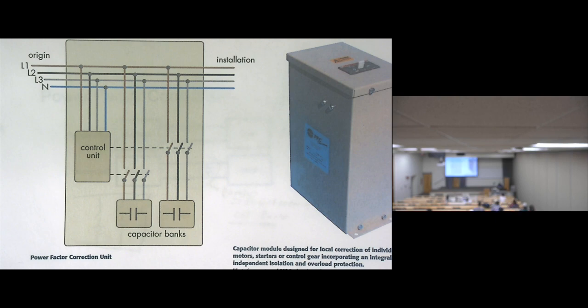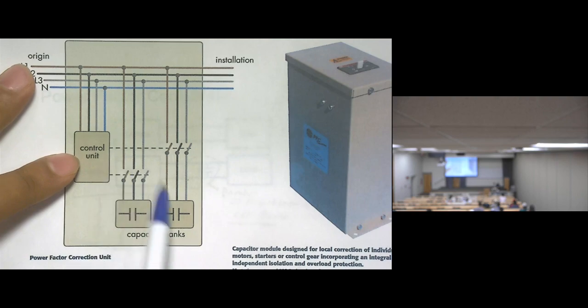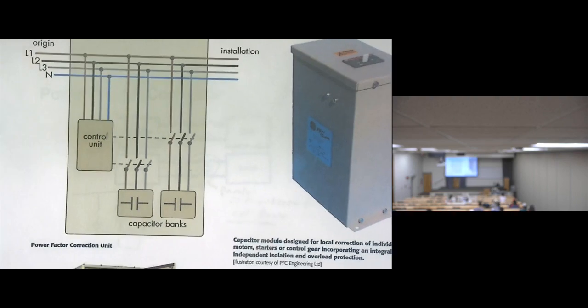Sometimes when the load is very high, we turn off these inductors. And if the load is still high and the demand is very high, then we need to improve the utility, so we insert these capacitors. Some electrical substations have this kind of device. This is not our purpose. Our target is to talk about the industry, but I'm just showing you that we use capacitors and inductors in real life to improve the grid. So this device is controlled to turn on or turn off depending on the demand.